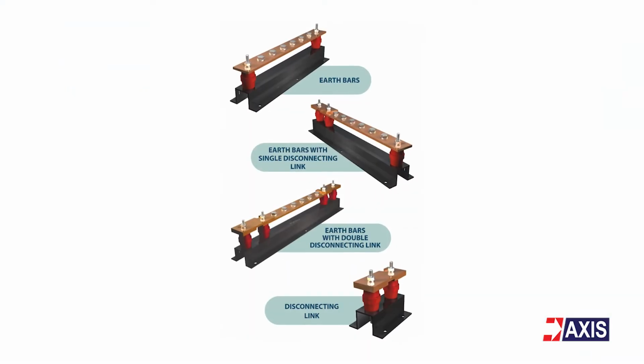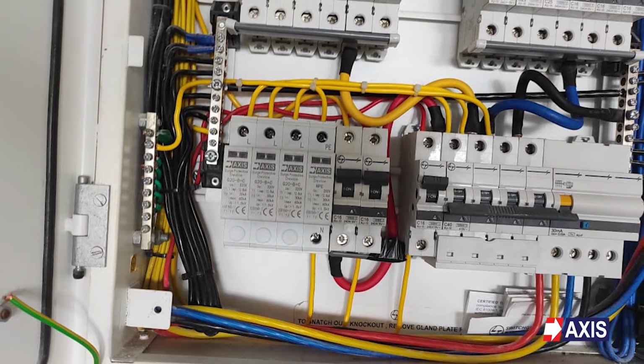The internal lightning protection system uses equipotential bonding and surge protection devices to ensure protection. As an example, equipotential bonding of all metallic surfaces at the border of each lightning protection zone can protect the next lightning protection zone from a potential surge.